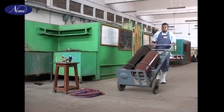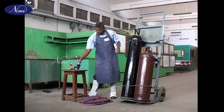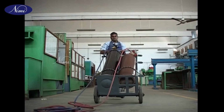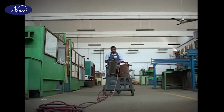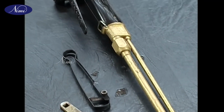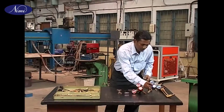Oxyacetylene gas equipment can be stationary or portable. What you are now seeing is a portable unit. The oxygen cylinders are tall and slender and are colored black. The acetylene cylinders are colored maroon and are short and stout. Let us now see the various components of the oxyacetylene gas cutting system.